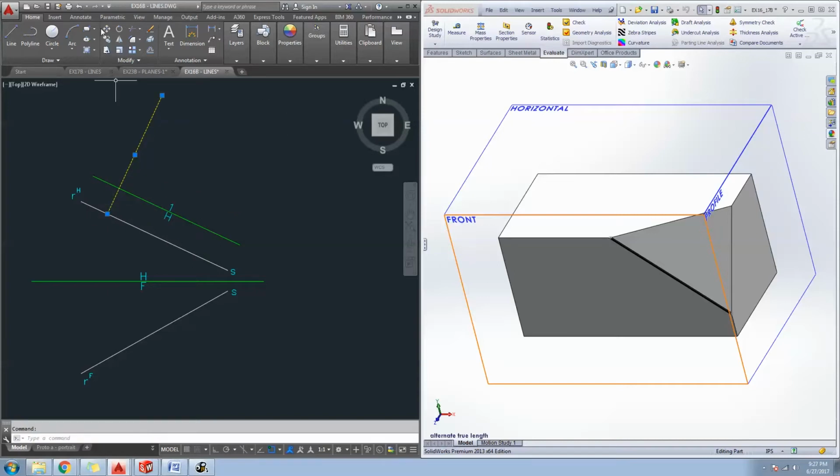I'm going to pick it up and move it over there. Then I'm going to copy it over to the other point S. Perfect. I'm going to type LEN for lengthen, DY for dynamic, and stretch out that folding line just a little bit so that it's bigger than the object. The box is bigger than the object it's supposed to be containing.